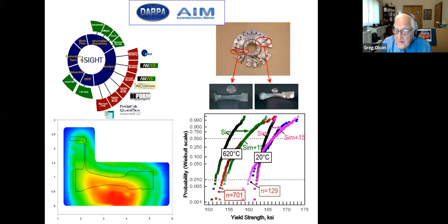The AIM project is where we first coupled our microstructure models to macroscopic process models in the context of process optimization of a nickel-based superalloy turbine disc. And for this, we initially built the PrecipiCalc simulator using a mean field approximation, but grounded in the CALPHAD system, which has now become the commercial product TC-PRISMA. But that was the necessary tool to meet the goals of the DARPA AIM project, and that was then integrated through the iSight integrator with the other tools of macroscopic engineering.